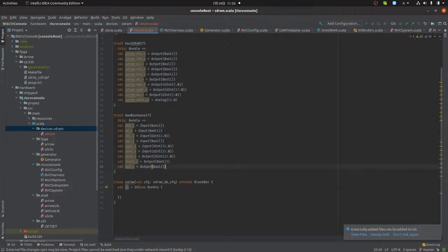Very simple Wishbone interface. That means that wherever they put the select and the CYC, sorry, the CYC more than anything, it will respond. It will be asserted until the ACK will be there. I don't know about the stall. I need to know what the stall does. I know how to handle a very basic Wishbone interface. I'm more used to RISC-V and the iLink, but yeah,